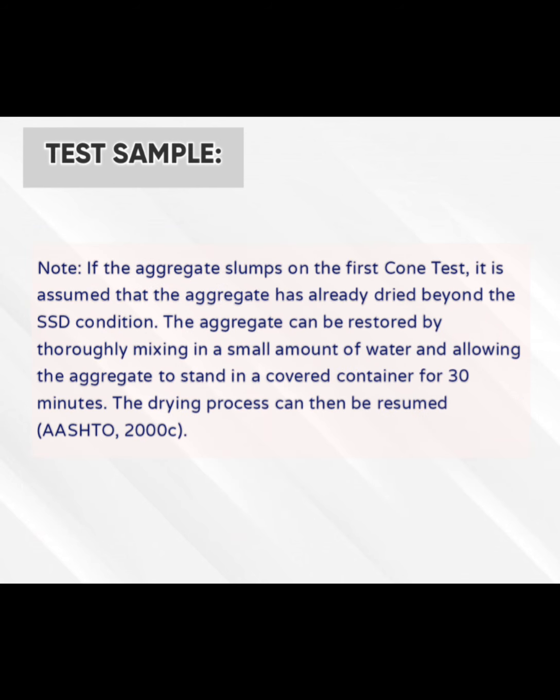So note, if the aggregate slumps on the first cone test, it is assumed that the aggregate has already dried beyond the SSD condition. So the aggregate can be restored by thoroughly mixing in a small amount of water and allowing the aggregate to stand in a covered container for 30 minutes.